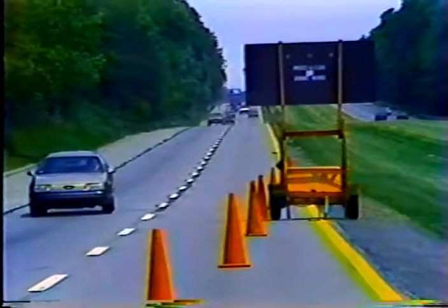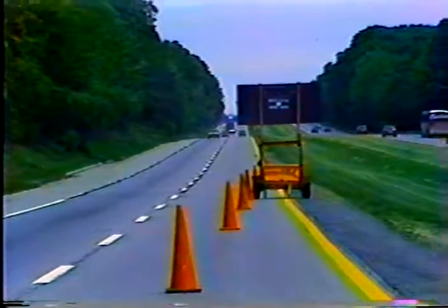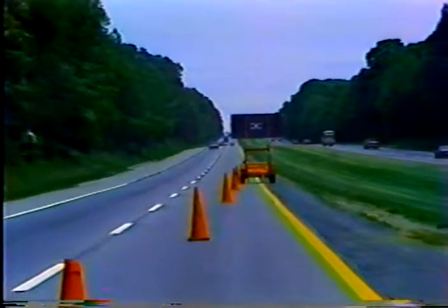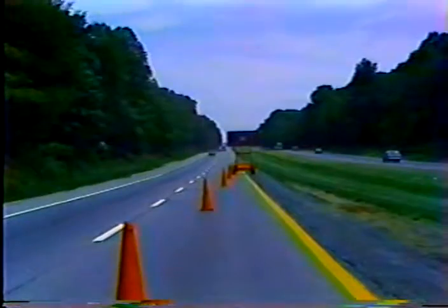Basically, you just want to make sure the contractor uses only approved devices that have been specified in the plans and that conform to the requirements of the MUTCD or your agency's own traffic control manual. For example, non-reflectorized traffic cones like these may work fine for many daytime operations, but you can't allow them for nighttime use. Here's another example. Flashing lights on barricades are good devices for drawing attention to isolated hazards. But for delineation, you'd use steady burning lights that outline the safe travel path.